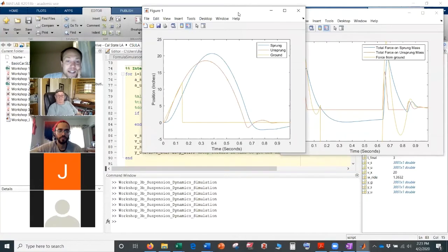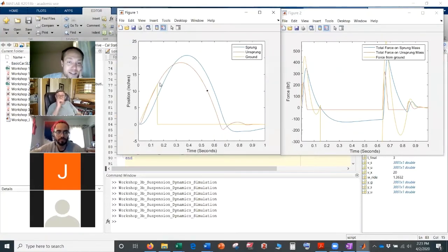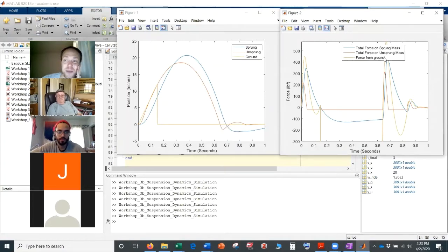And so what you see in this case now is you see the tire, it kind of initially gets hit with the ramp, but then it follows the ramp and it goes off the jump, right? So it comes down and at about 0.65 seconds, your tire hits the ground and squishes into the ground, right? And so you see from hitting the ground, right here, you just have gravity acting until 0.65, you hit the ground hard. And you see from going almost more than a foot in the air, you see about 600 pounds force, right? As you hit the ground, basically.